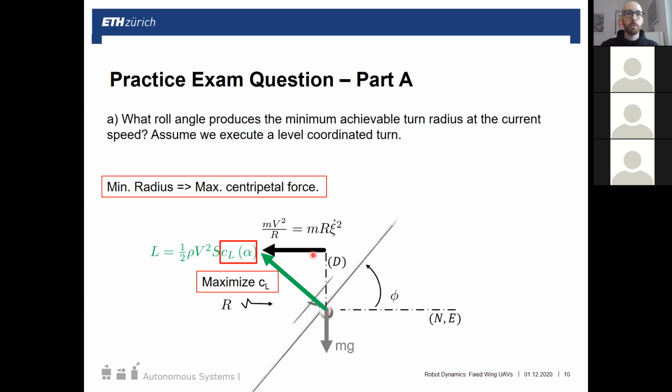Of course, so then if we increase angle of attack, we're shifting the body axis more and more and more up. So the body axis isn't any longer pointing directly out of the screen, but our airspeed vector is. So the lift is still perpendicular and lying in this screen plane. So it won't change with the angle of attack here. So we can still say this guy is directly lying on the screen plane.